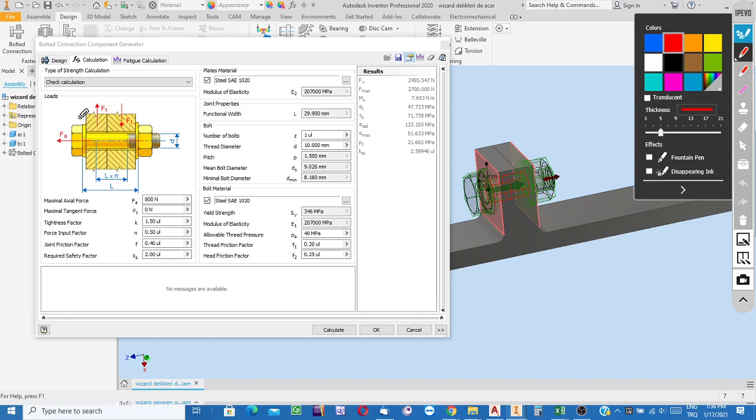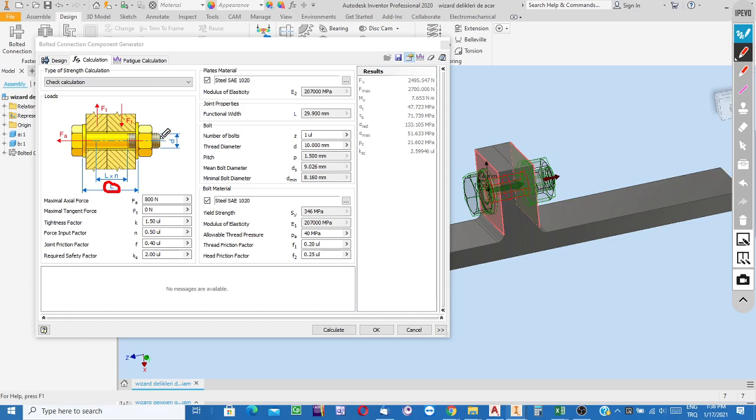Yes. Well, screw the nut against the bolt, and then make the distance L smaller, and of course, in the end there will be such a gripping force applied by the nut onto the components, and of course at the opposite side such a gripping force exerted by the head of the bolt.